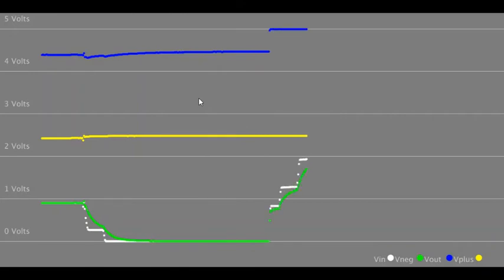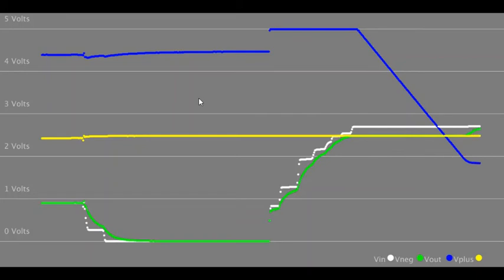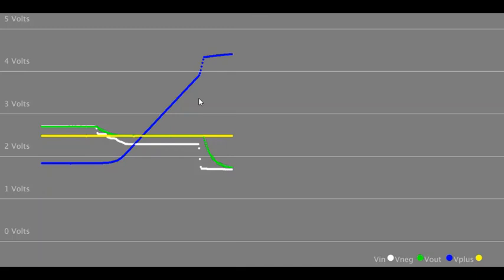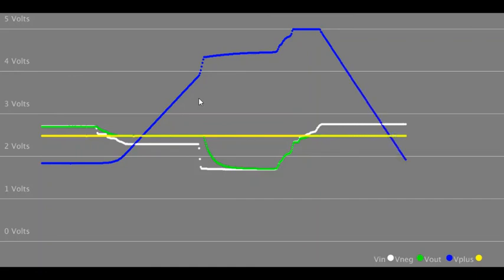And when increasing, when V out does not actually equal V in, or when V plus or V neg doesn't actually equal V in, the V out is integrating the opposite of that difference over time, and then once they become equal, it flatlines again. This is supported by the theory shown in solving for the gain in the circuit. The gain here is the integral of the difference, basically.